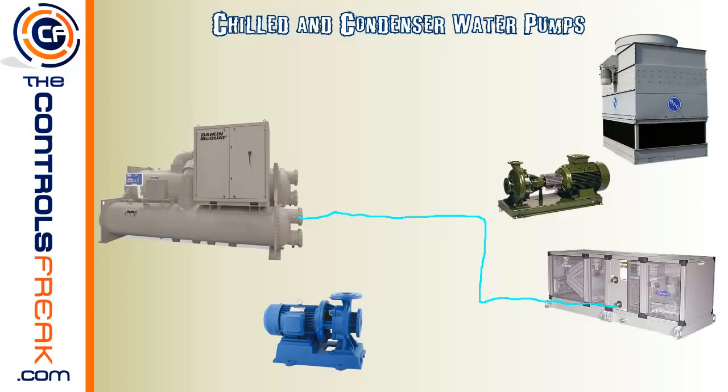Now we want to draw the water coming back out of the coil that's ready to go back to the central plant and get cooled down again. So that'll be this darker color here. And we'll send it this direction. And I'm sorry, pipes don't normally go on a diagonal slant like that, I promise. But it comes into the inlet of the pump. And in case you're not familiar with pumps, if you looked at this type of pump here, the inlet is actually going to be this horizontal one here. And there's an impeller in here, so you can imagine it like a boat propeller, but this is an impeller, and it will draw the water into the center portion of it and then spin it around and shoot it out the top here. And this is going to go right back inside to the chiller.